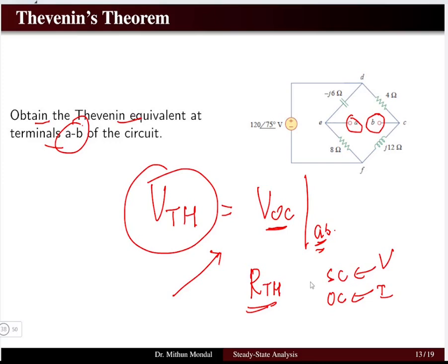We will not touch that. Only the independent voltage source and independent current source we have to short circuit and open circuit. So let us see how to solve this.